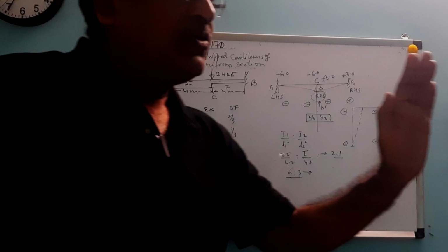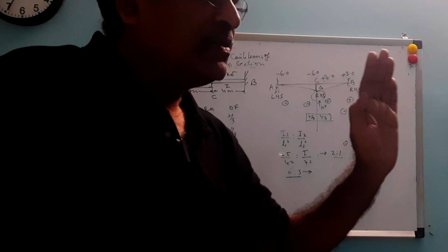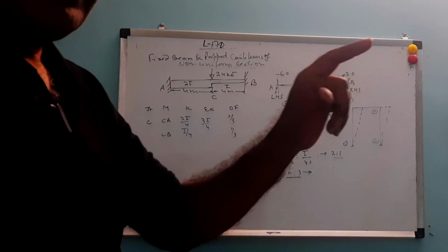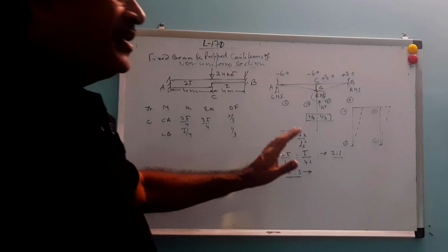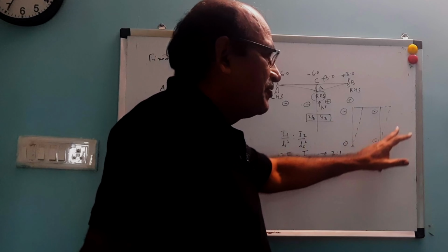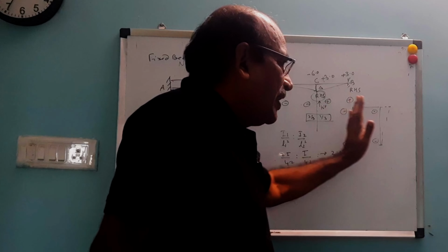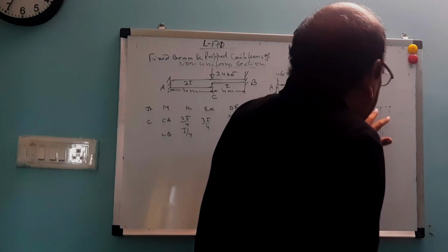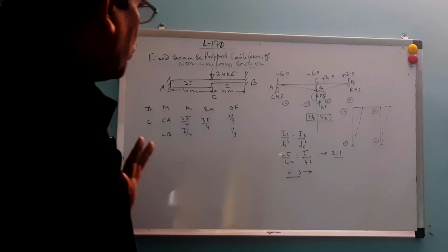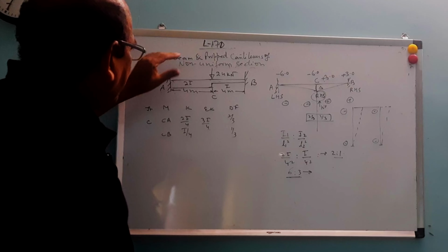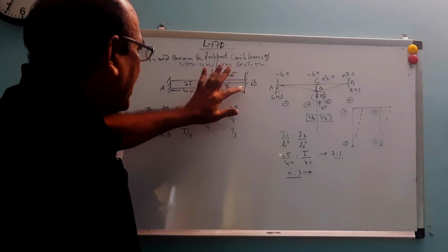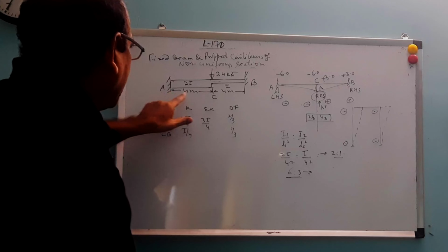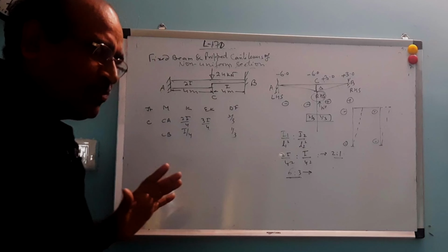There is a horizontal force pushing from left to right, making some sway, that is deflection, and according to that we get negative moment at the edges. So what will happen if, for this beam AB, at point C we adopt AC and BC as a propped cantilever?